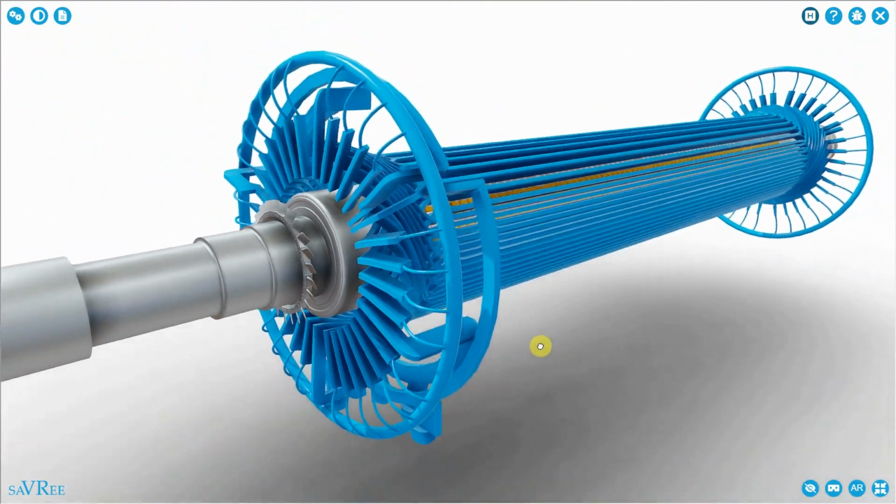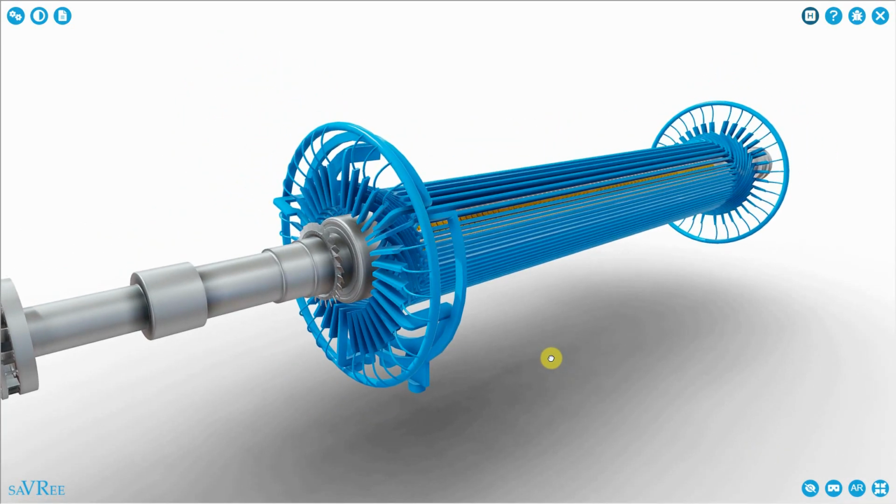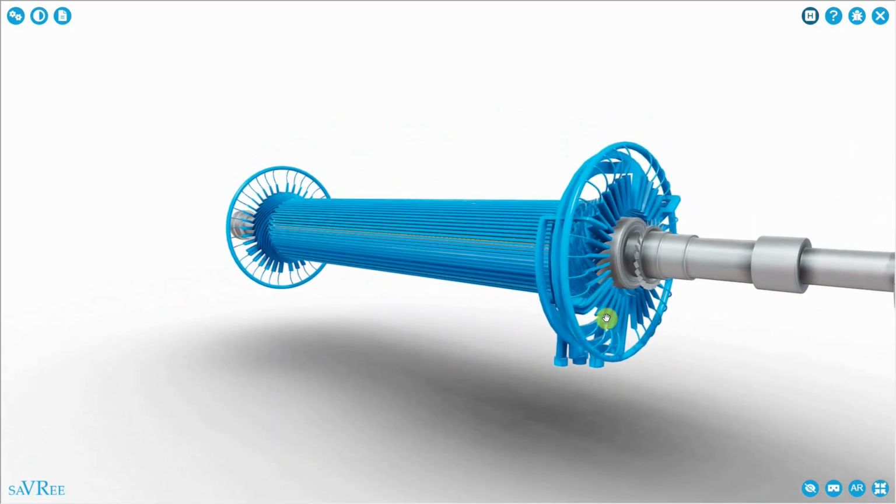The stator windings are quite interesting. They use conductive materials, mostly copper alloy, which is a mixture of copper and silver, but you can also use aluminium as well. The reason you don't use aluminium very often though is because aluminium requires a lot more space than copper, and we always want to keep our generator as small as possible.